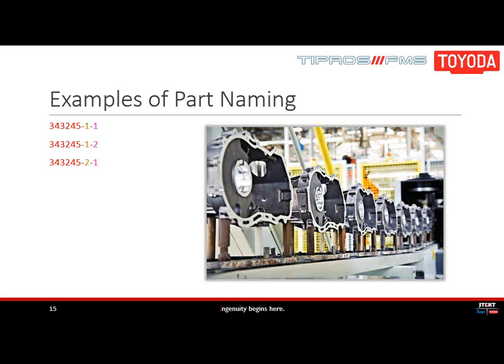The part would come out of the machine. The same screws that we had just drilled are used to then hold that to the fixture, and we'll remove the toe clamps to go back into the machine to be machined again. Now please note that this part cannot be removed from the fixture. That would mean something else. Third example, this is the second operation and the first process. So this would come out of the machine and it's ready for its second operation. You can unload it and then load it back onto a new fixture, and then it's ready for its second operation.